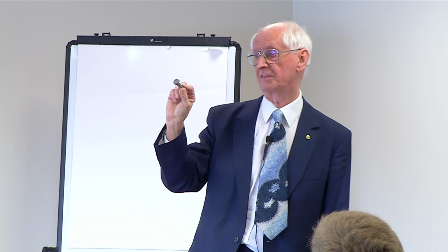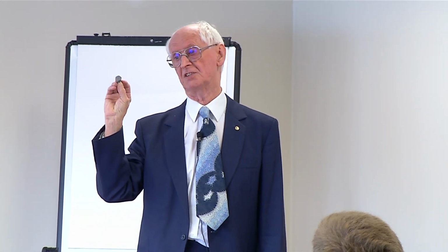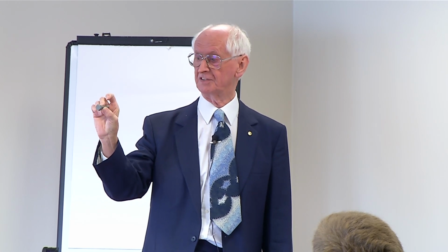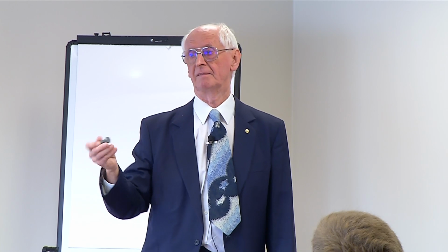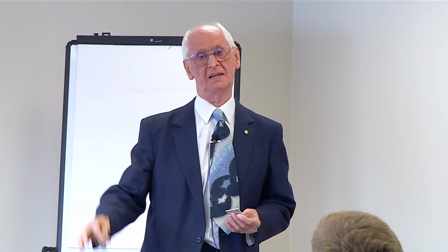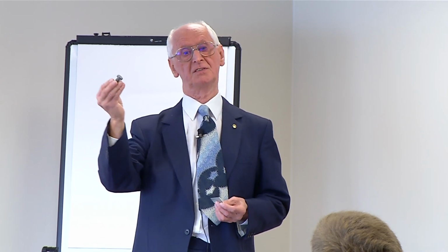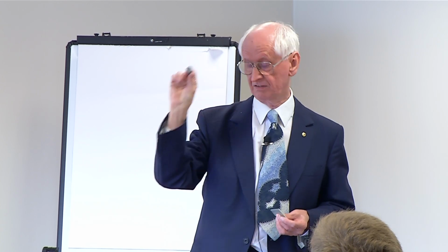And the reason is that this is hot dip spun galvanized. So the base metal, the steel, goes into a bath of molten zinc. The zinc forms an alloy layer with the steel, and as you take it out of the bath, then there's a layer of pure zinc on it. And they are very good.